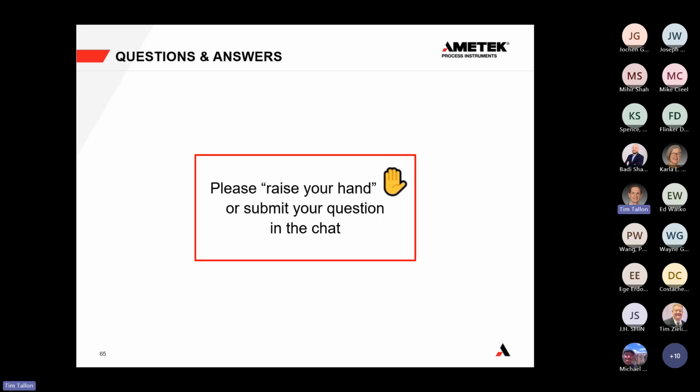So I think that's one way to improve the safety and also to prepare for variations in fuel. So yes, I think it is certainly important to monitor for fuel gas composition upstream if possible. And if it's not possible, I would recommend a higher excess air at the burner, a higher level of excess oxygen in the flue gas, so that you can be prepared for those fluctuations, especially where it's from hydrogen to methane, where methane needs 20% more air compared to hydrogen. Good question there.